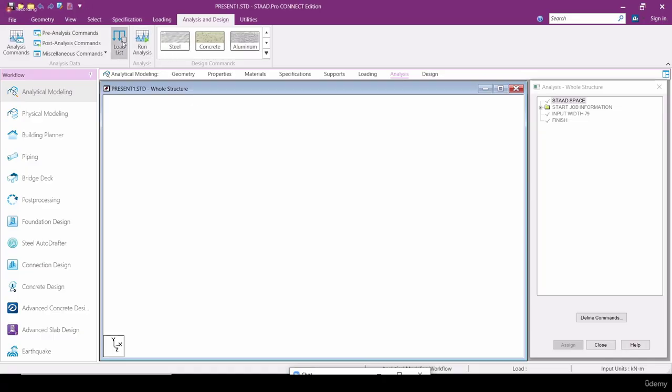So load list is nothing but a representation of load numbers. What are the loads you are going to give, the combinations in which the structure has to be designed. So load list is a command in which the load combinations have to be executed in our design. Okay, so load list is the particular command. It is the main command generally we use.